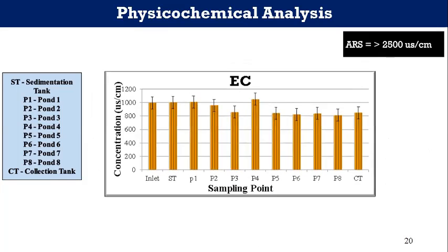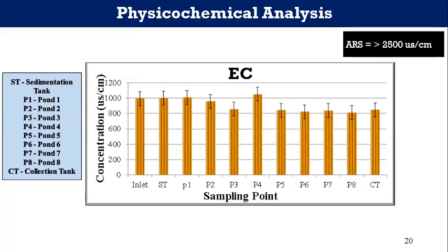Electrical conductivity, as an indicator of the total concentration of dissolved ions, is a valuable tool in assessing water quality. The graph shows a slight decrease in conductivity level, which may be due to a decrease in the concentration of TDS and the conversion of nitrate nitrogen to diatomic molecular nitrogen, as the concentration of charged ions decreases.